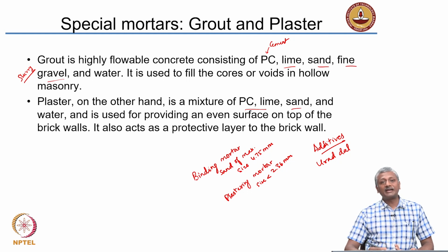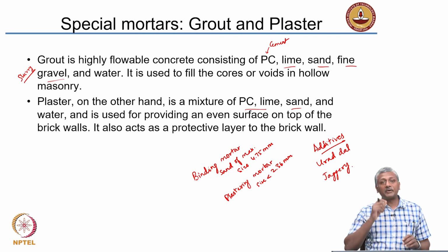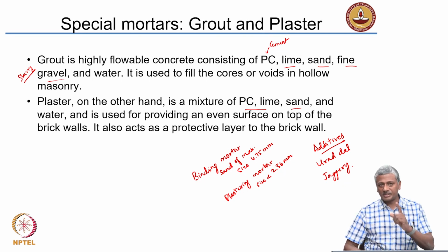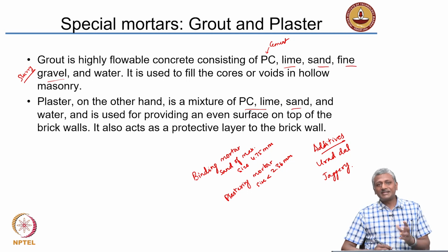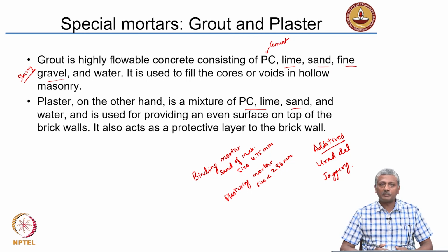In South, you will often find that jaggery is being mixed in the mixture of lime and water. They mix jaggery also, lime, mortar and water, and jaggery imparts a nice water retentive quality to the structure. So, depending upon the application and depending upon the geographical location, there are practices that have thrived, that have actually stuck on from age old times, which are still being followed, especially with the construction practices with lime. So, you will see that depending upon the geography, depending upon the location, you may actually get very different practices as far as lime mortar preparation is concerned.